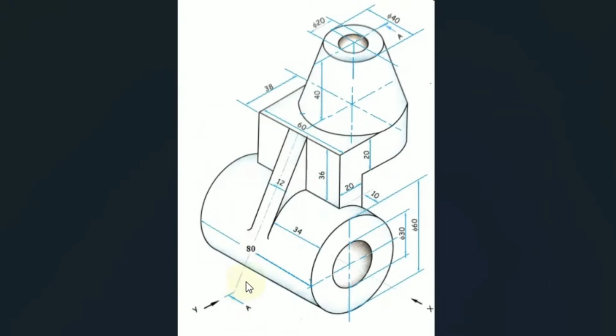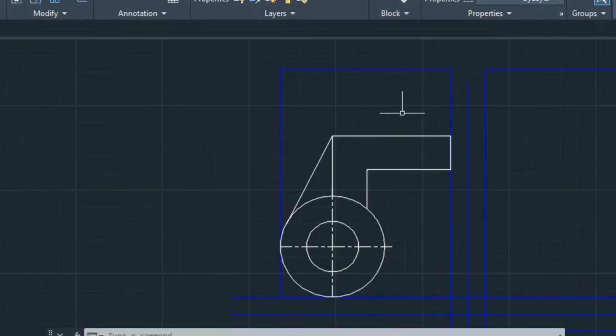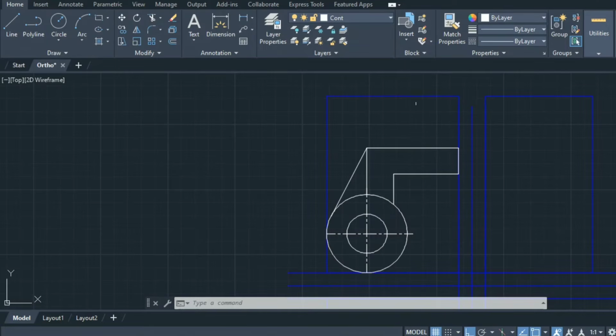Once this rib is made, now we will draw this frustum of cone. To draw this frustum of cone, we know that it has a base diameter of what? The 60 mm itself, as it is matching exactly with the semicircular part, and the top diameter is 40 mm. So to draw this 40 mm and 60 mm, we must have this axis line first. The axis line will be at a distance of again 30 mm from the right hand side point. That is the radius of this semicircle. So we'll measure 30 mm and we'll draw the axis line over here.